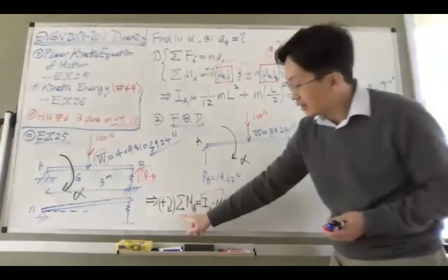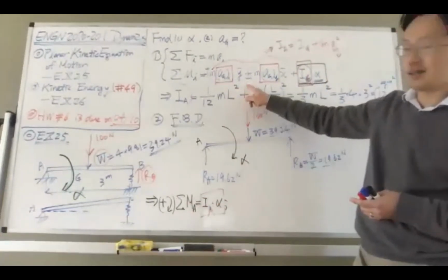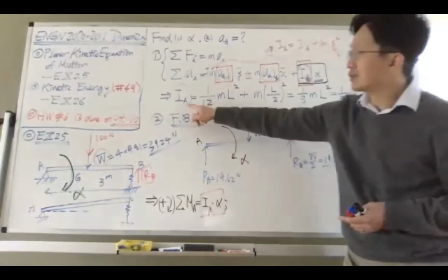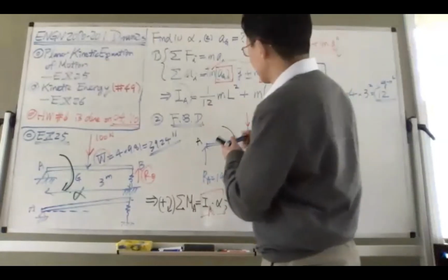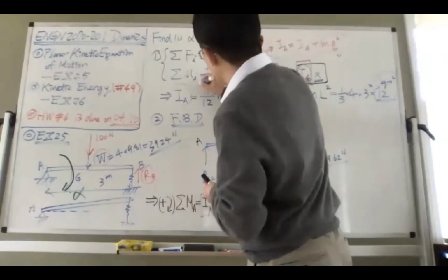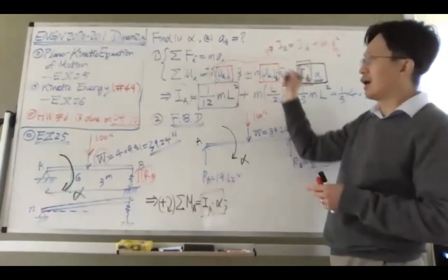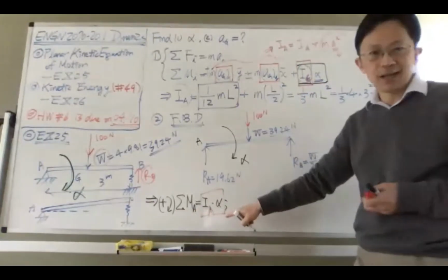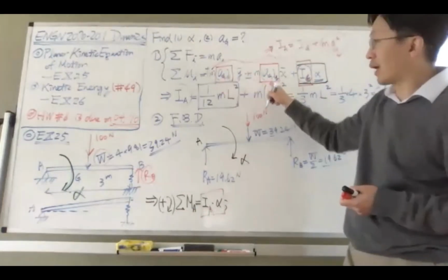Therefore, when we write down the moment equilibrium, you can choose to go this way. You say, I don't want to find out IA. I just want to use IG, which is just this one. This is IG here. But if you choose that, you will have to consider 3 terms on the right-hand side of the moment equilibrium, which may not be a good idea, right? Besides, we don't even know what is AGX, what is AGY. How can we use this?